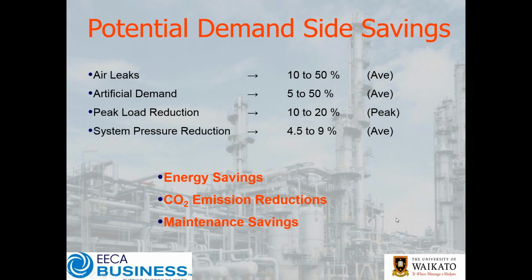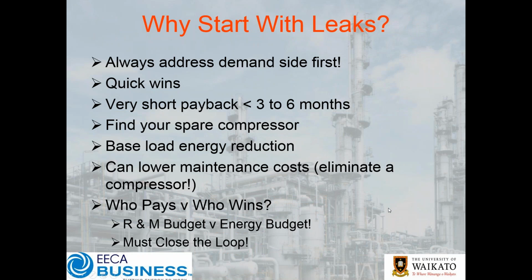So why are we going to start with leaks? Why have we put leaks first? Well, it's very, very important, especially with a compressed air system. You always, absolutely always want to start with the demand side first. Now, the great thing with leaks is they're very quick wins. They have a really short payback. In many instances, it can even be less than 3 months.